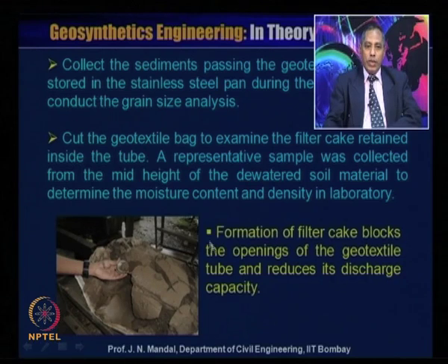Here you can see that we have cut the geotextile tube, and this is the filter cake. This is the formation of filter cake blocking the opening of the geotextile tube and reducing its discharge capacity.